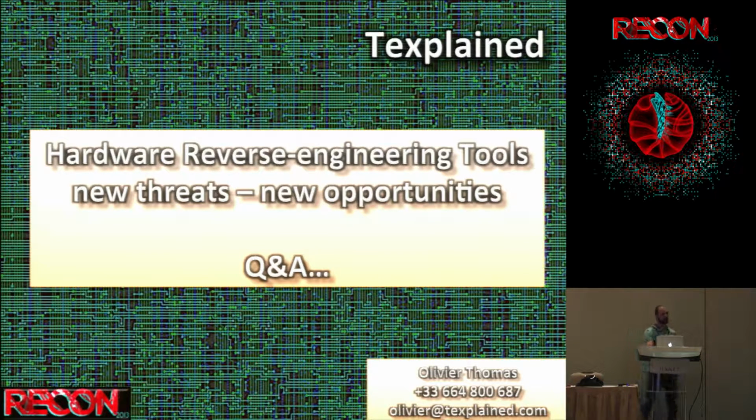Then, if you want to have also the capacity to perform the invasive attack yourself, you have to buy a FIB and a probing station. It starts to be really expensive, because if you want a nice FIB on the second-hand market, because you want to do backside since maybe you will have PUFs sometime or things like this, it's $500,000.